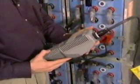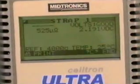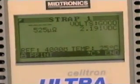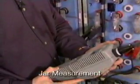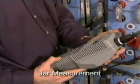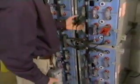After we have tested both jars and straps, we can review that information. For example, strap 1 reads 525 microohms. We expect to see a slightly higher measurement of the jar compared to the strap measurement. We expect the conductance measured to drop when we measure the strap.